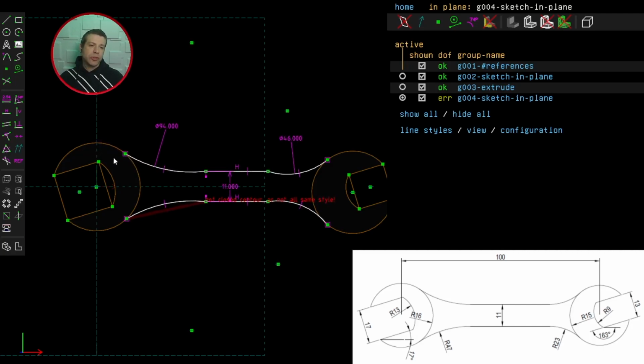As I drag this point, it eventually becomes tangent to the previous sketch. So this point has to be somewhere along this arc. And there's an easy way of doing this in SolveSpace by clicking on this button here. But in order for us to use this tool, we have to have 2 arcs in the same workspace. So I need an arc that represents this circle in this workspace.